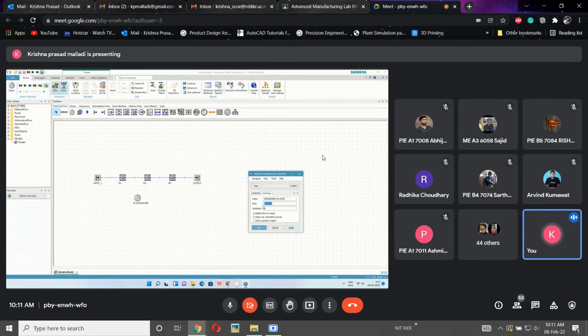If you want to run the simulation for 2 days, then how will it be? Now you tell me. I want to run the simulation for 2 days. Sir, we have to write it in a verb format. 2, 1, 2, 3. See here. Apply. So 2 days, 00 hours, 00 minutes, 00 seconds. Or else I can define it like this also: 24 double colon. It means 24 hours. If I click like this, 1 day.